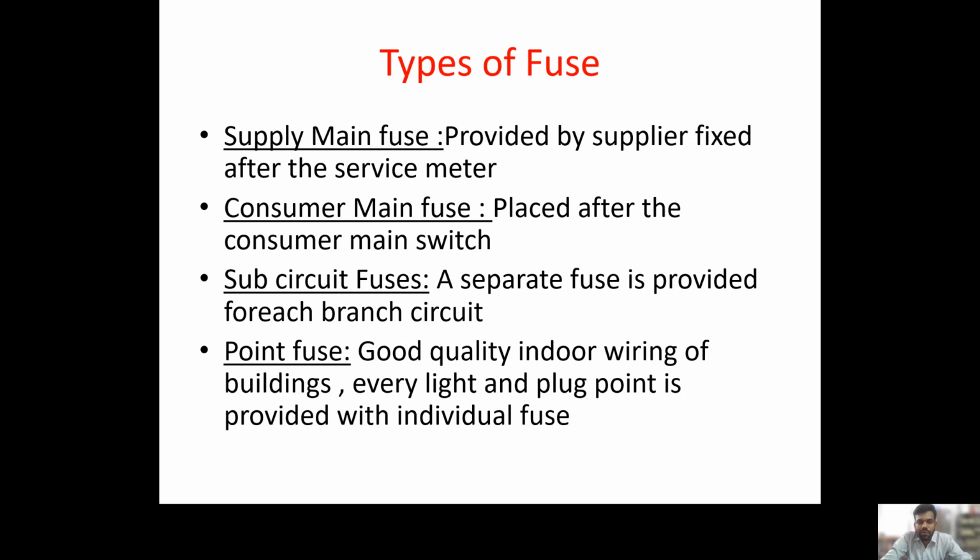The next thing is the point fuse. In a good quality indoor wiring of a building, every light and plug point is provided with an individual fuse. That is, if you need good quality wiring indoors, then we need to provide fuses at each point. That's why every light and plug point is provided with an individual fuse.